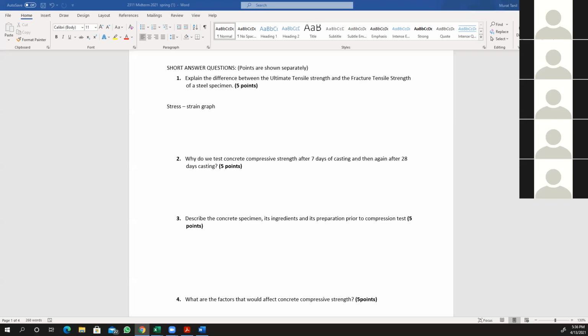Concrete starts shrinking, and tensile forces develop inside the concrete. When it shrinks, you will see cracks in the concrete. And more than likely, the concrete that you are looking at, let's say a column, a girder, or even the concrete pavement on New Orleans roads, you see the concrete pavement has 8-inch thickness, and it has rebars. The rebars are made of steel. What happens when water and steel get together?